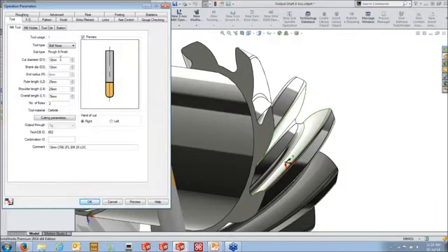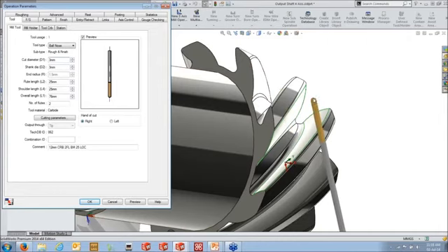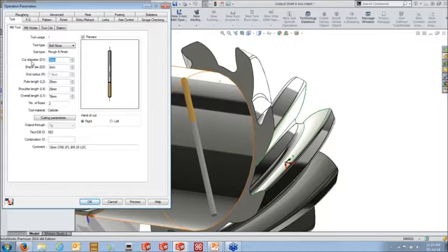So first thing I like to always do, make sure my tool size is going to be something appropriate towards the geometry. Now we've got a small radius down at the bottom here, so we are working in metric in this case, but we could just switch all our tools in here. If we had a certain tool size that we wanted in imperial, maybe it was like 1/4 of an inch, we can actually just type that in here, and it will convert all those over for us.